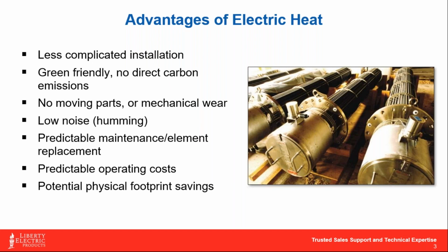The only moving parts that might be in conjunction with something like an air heater might be a fan blower with it. The one thing I like as well is that you can test elements for their longevity, and depending on what the resistance readings are coming back, you can actually predict the rate of wear on these elements and proactively change them out before your process is disabled and you're down and losing money. So I think that's a very important feature.